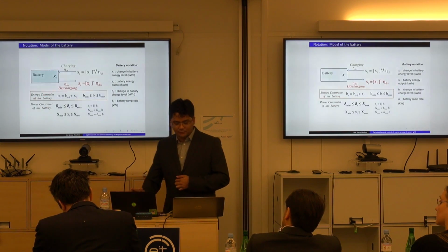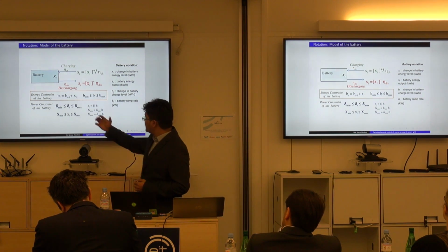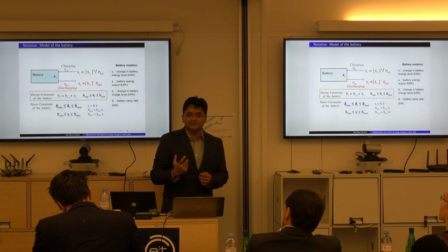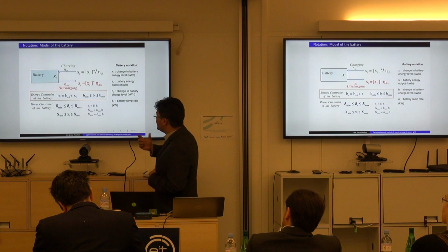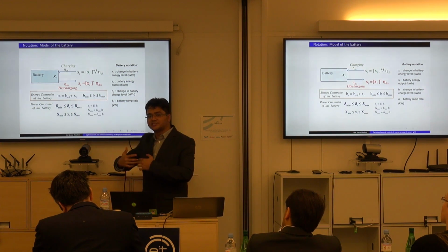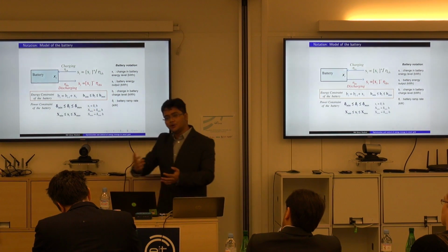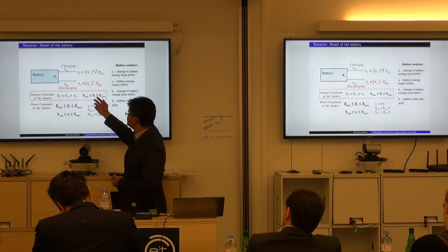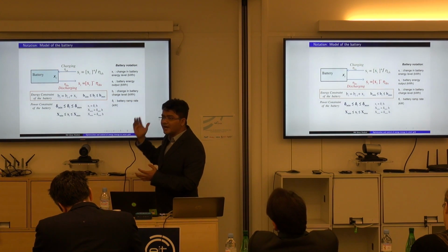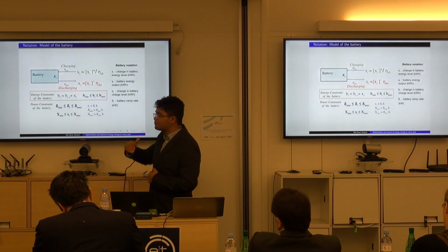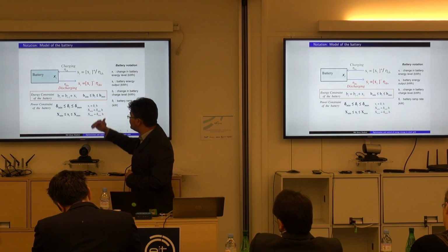First we discuss the battery model. Xi denotes the change in the charge level in the form of energy at time instant i, and Si is the output power seen by the grid. Si during discharging will be lower than Xi because of the discharging losses, and because of the charging efficiency losses, Si will be higher. So more power is supplied to the battery for charging because of the charging efficiency losses.